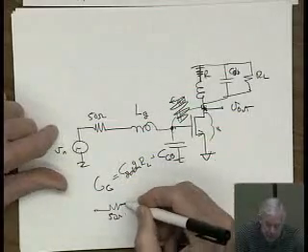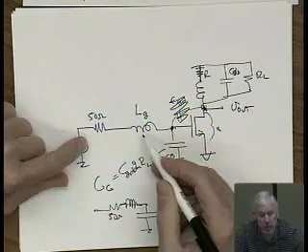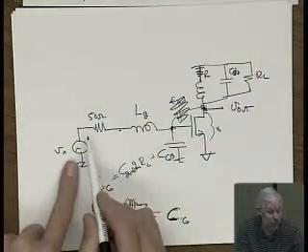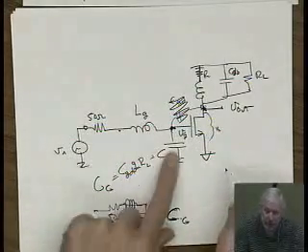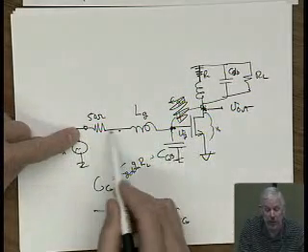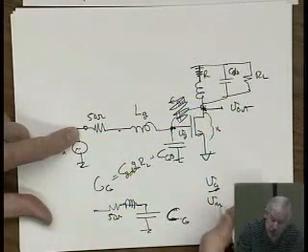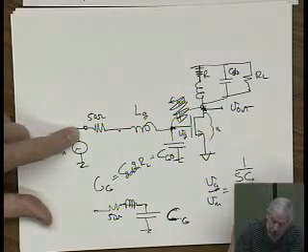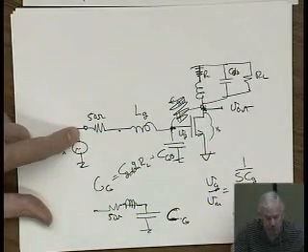But what happens if I use one of these inductors right here? What I can do with that inductor now is let's calculate what happens at this point right here, VG. We really have a voltage divider between this capacitance here and this 50 ohm and LG, so let's write that. So V gate over Vin is equal to 1 over S CG, S is just J omega, Laplace transform, okay.